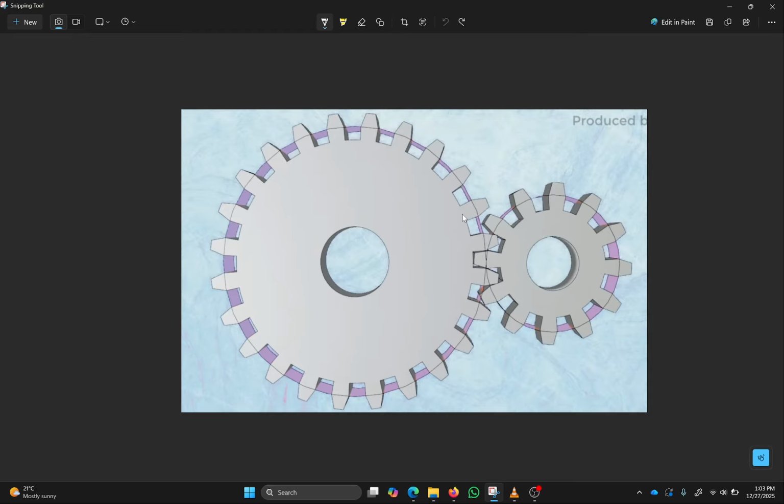We talked about rolling contact, where the point is always in contact during velocity analysis. So whenever gears mesh, these imaginary circles are the ones that remain in contact and are rolling. That's why these circles are so important. They are always tangent to one another, and all the calculations we will do will be done on these circles. Calculations for gears are mostly done on the pitch circle. So: addendum circle, dedendum circle, pitch circle.